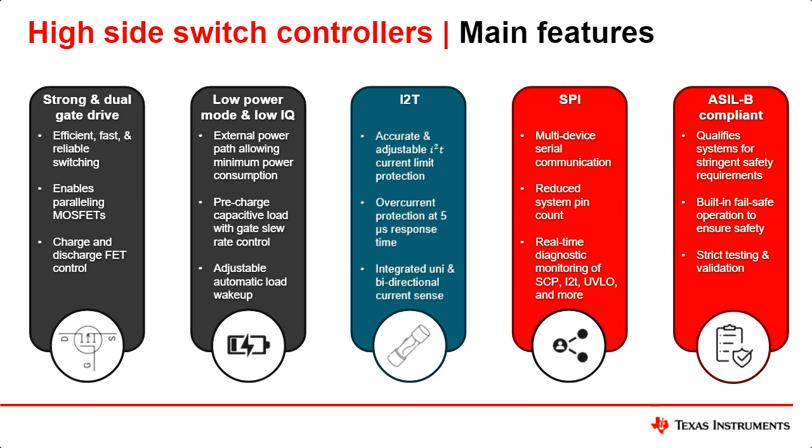And then low power mode: as we start seeing more applications with power at all times, and the fact that these devices are so close to the power source, we need to integrate a low power mode. So features like keyless entry, remote start, or safety alarms are always on, no matter if the car is off. And then the device slowly transitions to a fully on state when the car is ready to turn on.